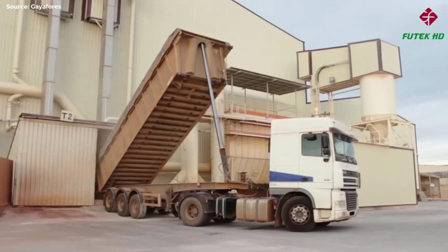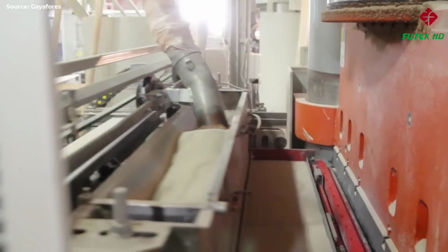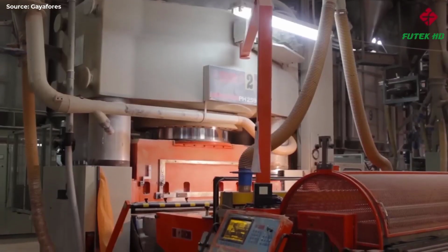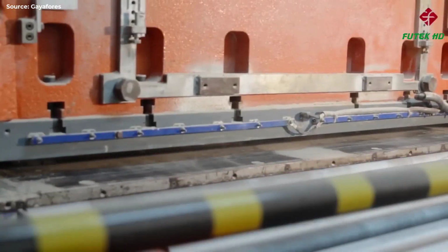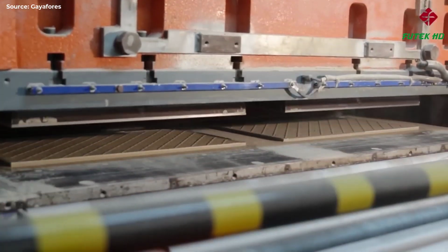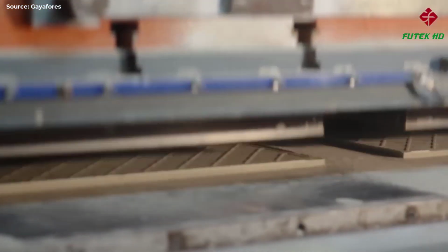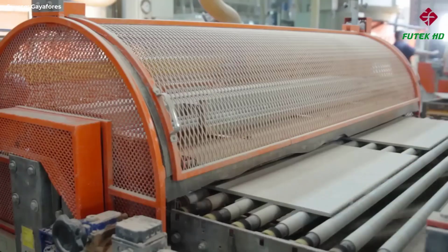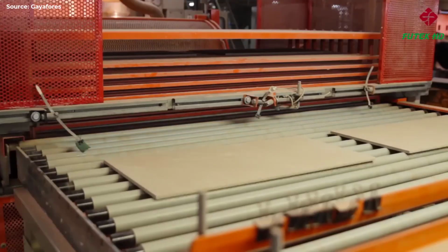Spray drying and pressing. After milling, the raw materials are transformed into atomized dust through a process called spray drying. This step removes water rapidly, resulting in spherical and hollow granules essential for pressing. The granules are then fed into a silo and subsequently into the press, where they are compacted under high pressure. This pressing process breaks the granules, allowing the particles to re-adhere and form a cohesive tile with sufficient mechanical strength.